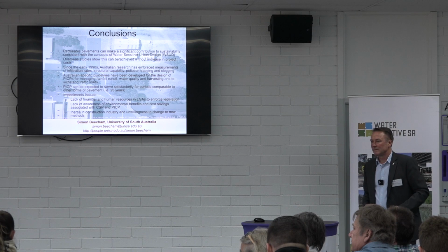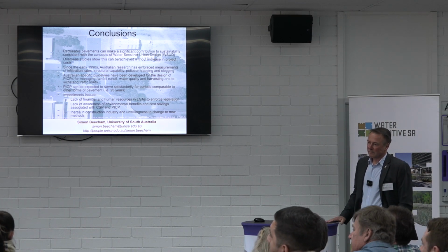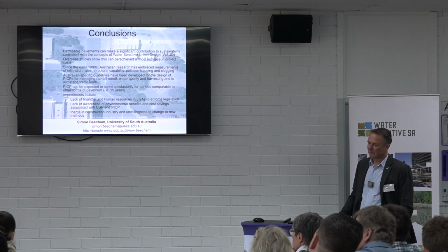Hello. When you're comparing some of these permeable pavers to other surface types, has there been research done on runoff coefficients? The runoff coefficient for asphalt is close to 1, but for permeable paving, you don't actually have to consider runoff coefficients per se.